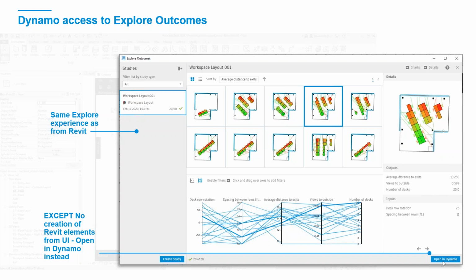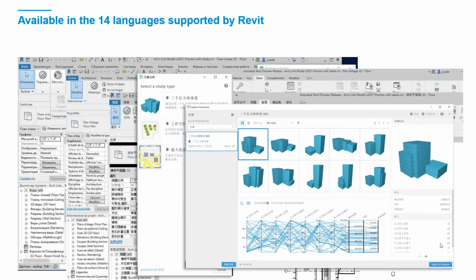It's not going to do the same thing when you come to generate it. So for those of you who use Dynamo and Revit, you'll run it, and I'll be doing it in Revit in the background. At the end of it, it will create the studies, but you're going to have to open it in Dynamo and then run it to generate the final option. So that's just a little workaround if you're not on the Generative Design for Revit 21 in the AEC collections.